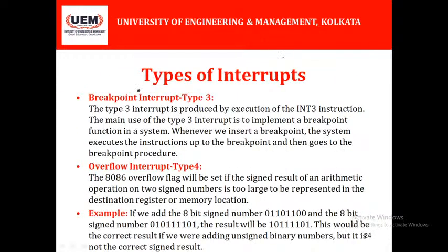There are several other types of interrupts, such as the breakpoint interrupt, that is the type 3 interrupt. This type 3 interrupt is provided by the execution of the INT3 instruction. INT3 stands for interrupt 3 instruction. So it is a breakpoint interrupt. What is the main use of the breakpoint interrupt? To implement the breakpoint function in the system. Whenever we insert a breakpoint, what happens? The system executes the instructions up to the breakpoint, and then it goes to the breakpoint procedure.